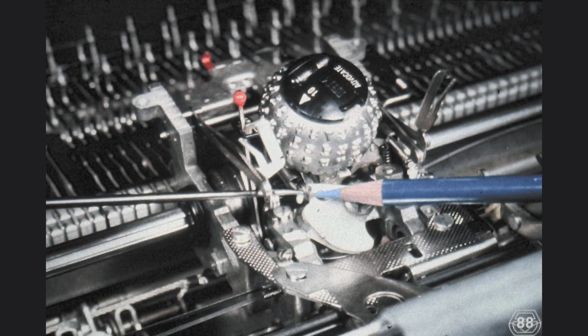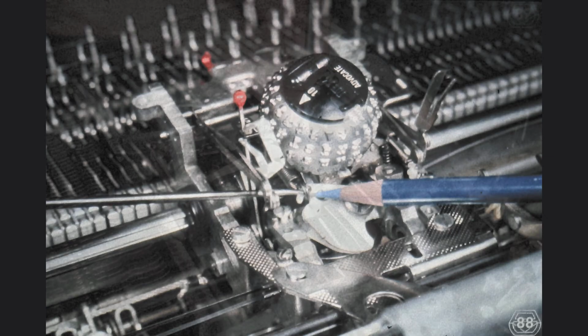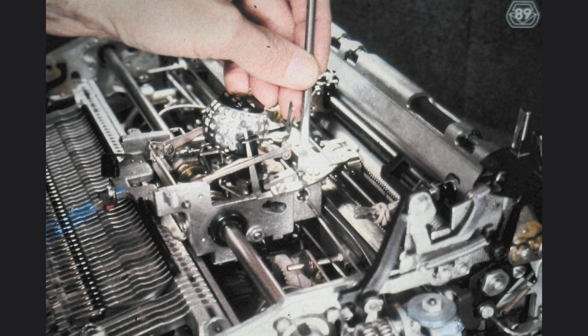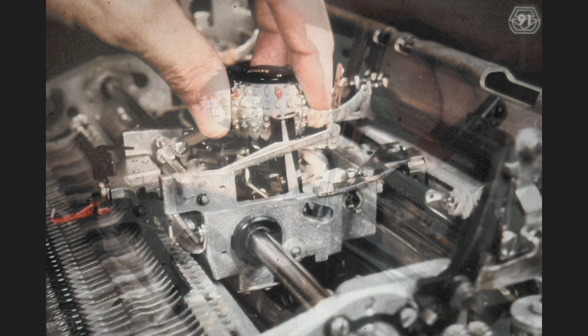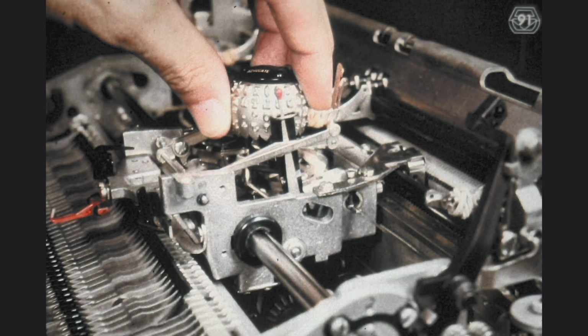By disconnecting the tilt spring from the tilt pulley indicated here, we also remove that spring tension. Take a moment to perform this step as well. Since we have removed the spring tension from the tapes, we are now in a position to remove the anchor screw from the tapes. Let us do that now. Once we have disconnected the tilt tape, we can temporarily reinstall the rotate tape. A pair of tweezers is a handy tool for this job. The rotate tape has been reconnected to the anchor.